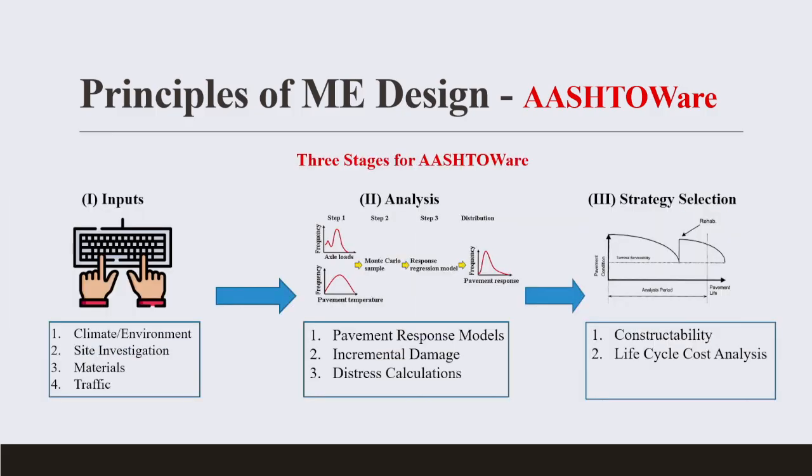Now, these are just inputs explaining the various things that I've talked about, and then you now deal with issues about constructability. So here we are now dealing with constructability, life cycle analysis. No, I explained that earlier on. You are dealing with what will happen in 5 years, and you can actually see what will be your percentage of cracks, what will be your rut depth. All those things will be predicted, and your strategy that you can do, and that's now the difference within the difference that we have.